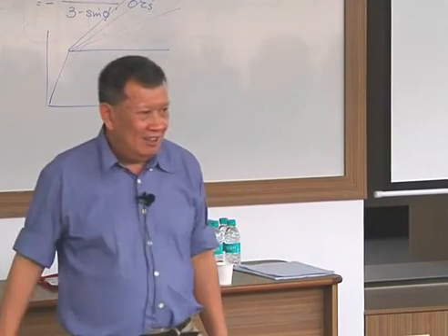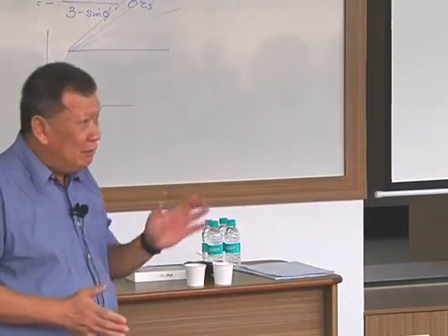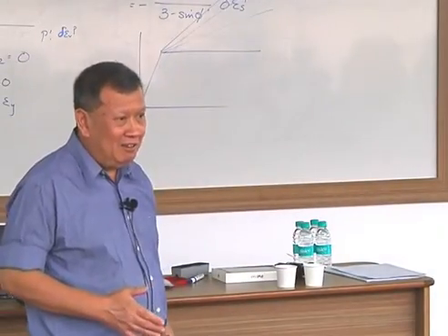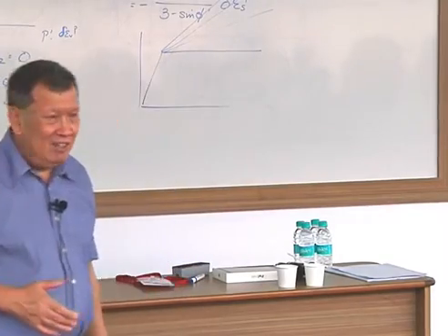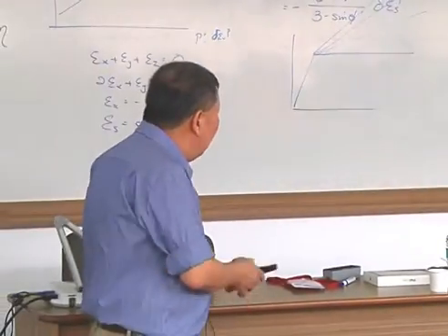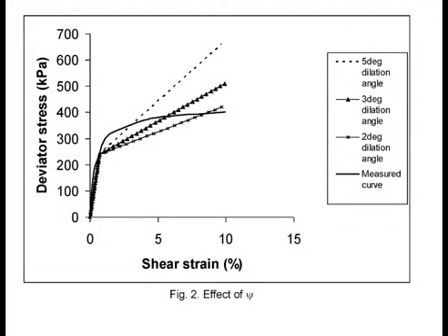Because when you look at the stress strain curve, for the 5 degree the gradient is pretty high. It's not low. Post-yielding is still very high. You can look at this thing. That's 5 degree, the top curve. And it's very high. As an engineer, you're saying that this thing is only conservative up to a strain level of 2.5%. Are you comfortable with that? I would be more comfortable with something like 10% strain. So if you ask me, I'll probably use 1 degree angle of dilation.